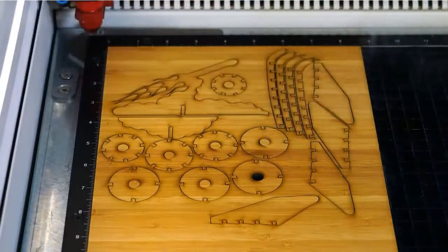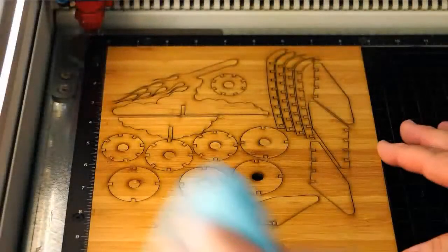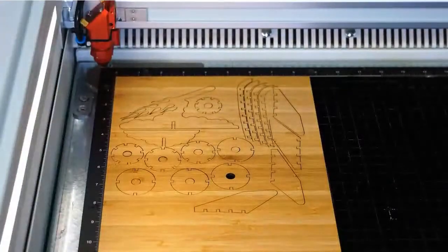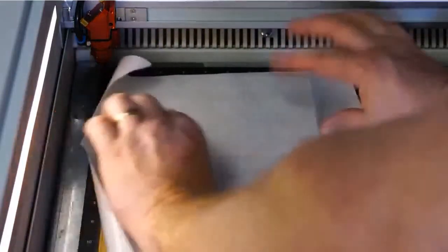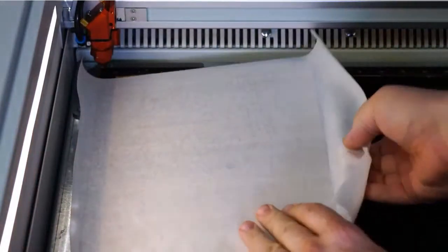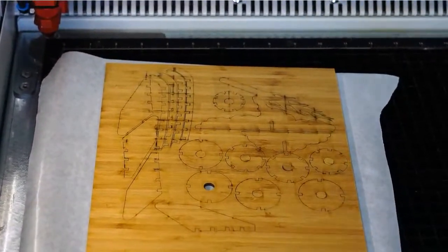Once the file is cut out, we will then go ahead and wipe the surface. I do recommend all wood is pre-finished so that the residue can be wiped off, because the laser will produce residue on the front. In a case like this, I will place a piece of transfer tape over the surface of the wood to pull out all the parts, but also to be able to flip them over and then wipe the backside of all the parts individually or very quickly. So this is a quick and easy laser hack for working with those products.